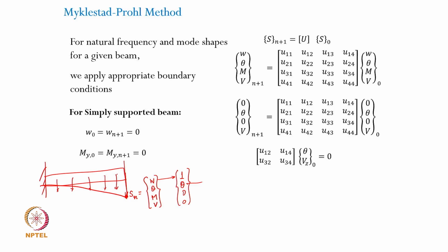Currently we are going to restrict ourselves to just the eigenvalue analysis of these problems. The advantage here, as I said, is that no inversion of matrix is required, and irrespective of the number of segments, the matrix size still remains 4 by 4. The matrix size is the most important plus in the transfer matrix method.